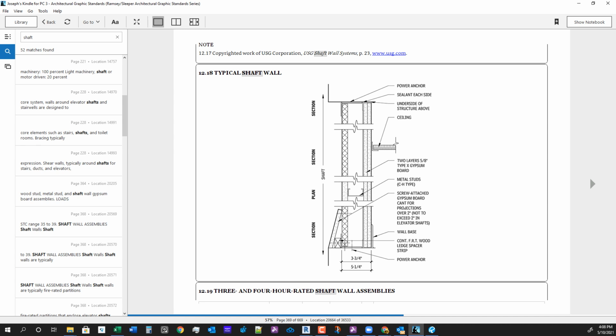Often this will be this kind of assembly here. It will be floor to floor, and they have this little gypboard angle here that you would install before you sealed it up, just so that nothing can sit on that ledge. You can see the 2 layers out here, and then this layer of shaft core board.